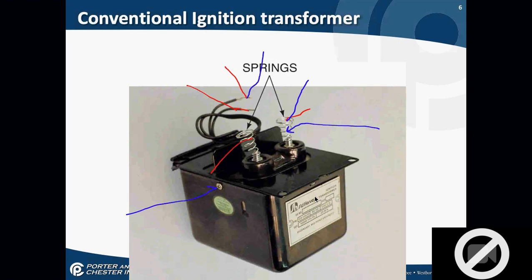By these readings, have I checked everything about the transformer? Yes. So what if I get everything that I'm expecting on this transformer? Then it should be good for use. Okay, but the burner doesn't run. What am I going to check? Check your wire connections. That's a very good possibility. The path itself, the entire path.